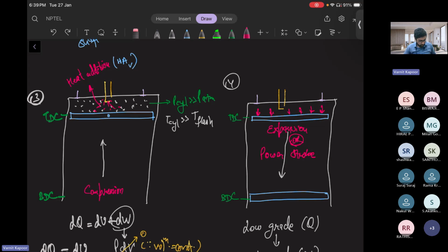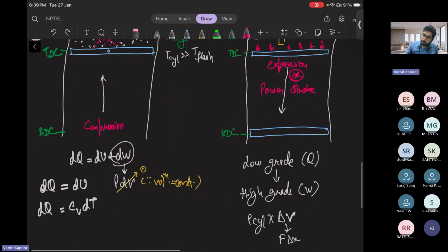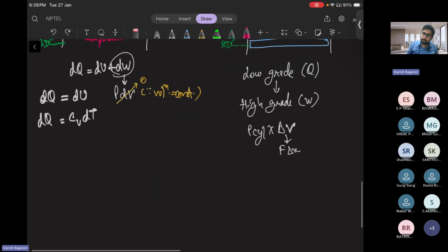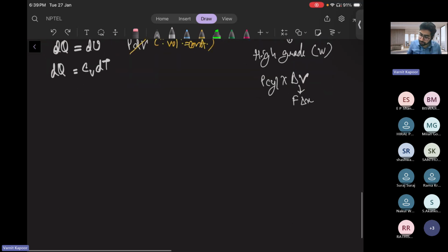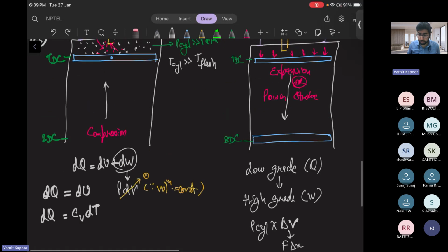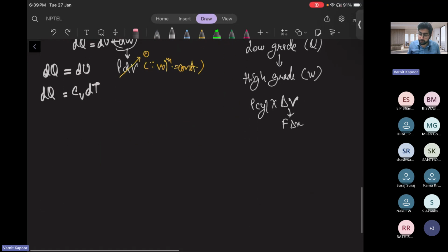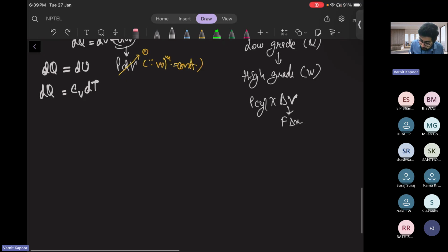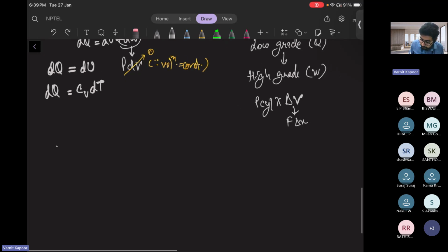Anyone else? Now again, the system has an inertia. So this piston will now move above. Let us see the next scenario. What happens? That is nothing but your exhaust. Till now, all the valves were closed. All inlet and exit valves were closed. You got the power stroke. But now one of the valves will open, that is your exhaust valve.